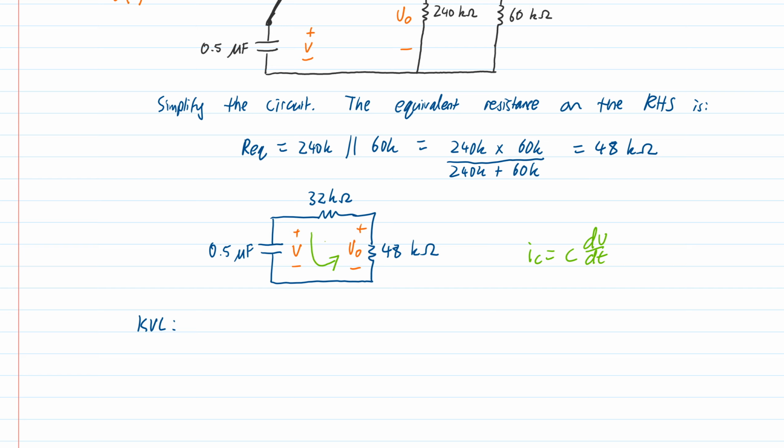So from the perspective of that capacitor, I should have a current labeled that goes from positive to negative. If I had labeled the current the other way, I would need a negative sign in my equation for the capacitor. So I'm going to label it according to conventional current, and when I do KVL, I will go in the direction of this I that I've labeled here.